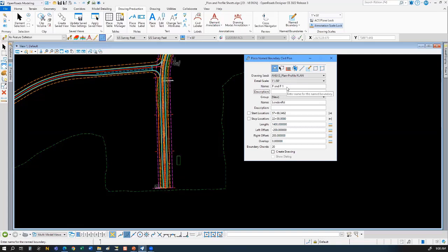And then the third one, and this one really got me along the way for many, many days before I figured out what was going on. Do not, I repeat, do not, when you use the name here or the name here, use an ampersand character, the and symbol. So I'm talking about this thing here. Do not use this in your names. For some reason, when you do that, the software doesn't recognize it. It locks up everything, and it does not allow you to produce sheets.